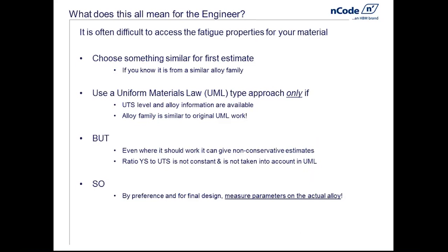From Arizona to Zambia, as I put it, the basic metallurgical solutions remain the same, and it doesn't matter what the nomenclature is. We will add silicon to make the casting alloys more fluid, or we'll add chrome to make it harder, or stainless, or whatever. So even if the numbers that appear on the screen are not the same, it's quite likely that there will be a similar alloy family that you can use.